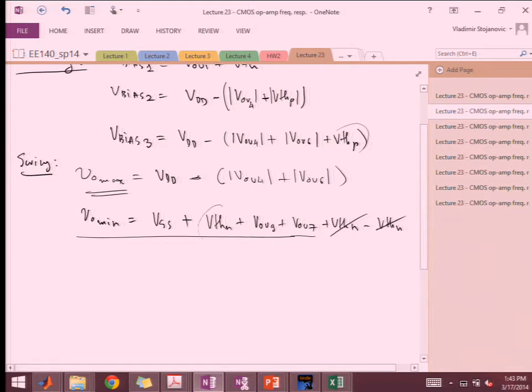Notice that I have a little bit of a problem here, right? This VTH. And this is kind of well understood because when you look at what we talked about, cascode current sources, this was the price, right, for the cascode. Now, what did we use to kind of alleviate this? That was part of sort of the biasing circuit, right? That was on the side of some other cascode topology. Maybe people remember.